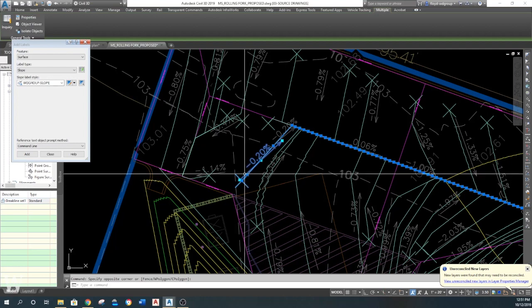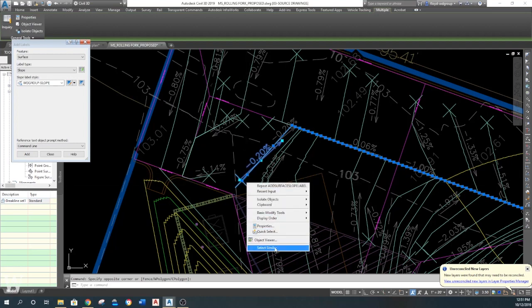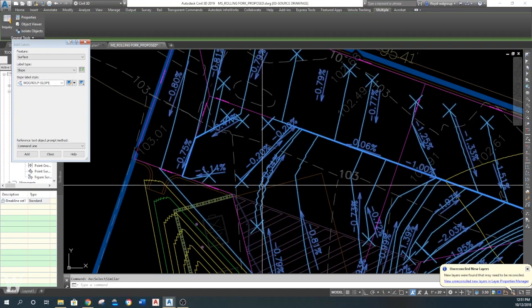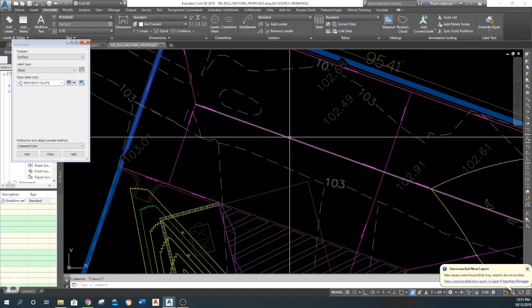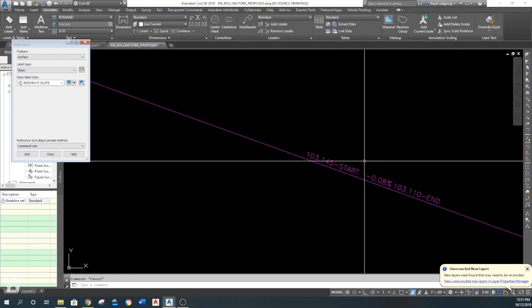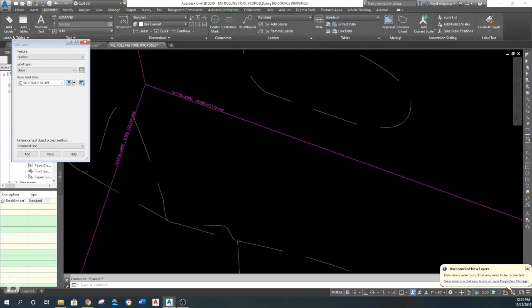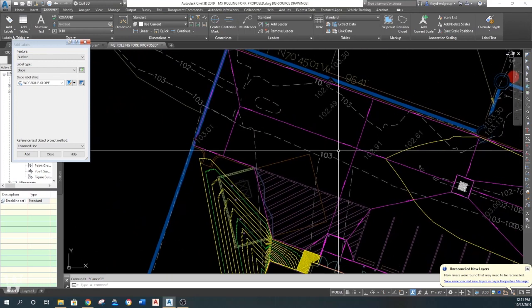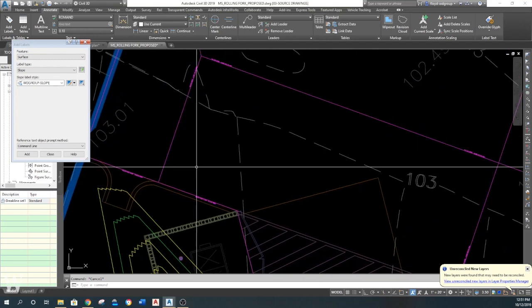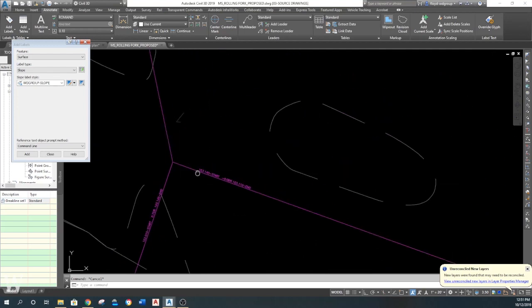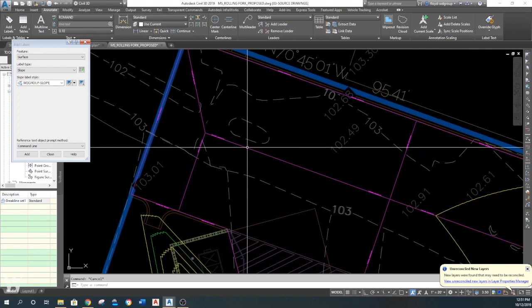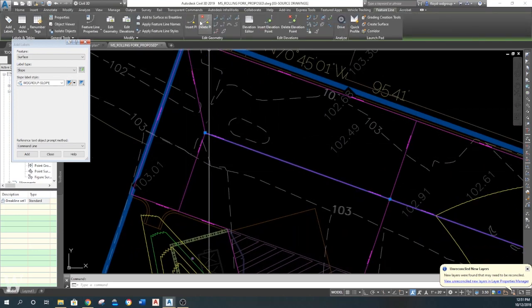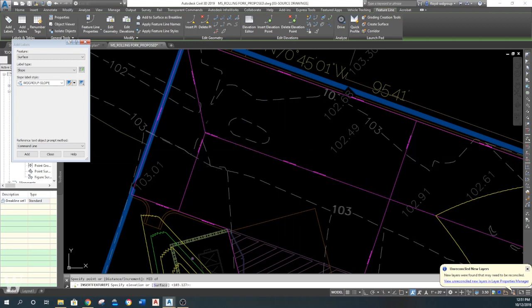So I'm going to click on the slope arrows and the water drops. I'm going to hit select similar because those are the only things on those 2 layers. Hit erase and clean that up. Now I want to come in here and look at that, and that says it's 0.808. I should have known I had a problem right there. So how's the best way to do that? Well, that's 0.75, that's 0.75. So really probably ought to just come right here about the midpoint of that and put a new PI in.